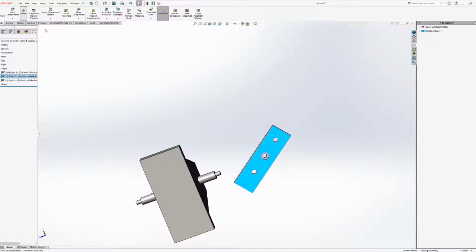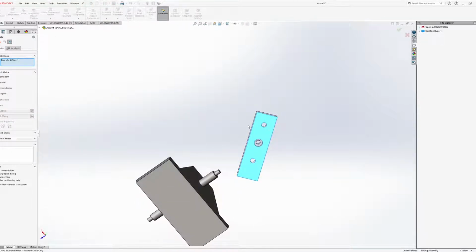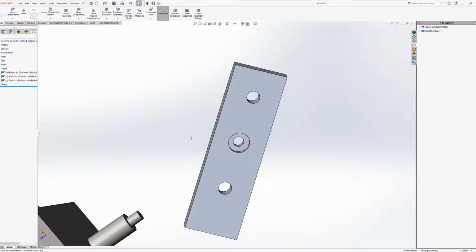I know some of you are probably yelling at me already. I said we don't want this kind of nested structure of mates. However, sometimes, and oftentimes, it will be acceptable. So yes, generally speaking we do want a common reference or a common mate between all the other parts, one thing expanding out to several different parts, but this is okay. This is acceptable. We'll be able to gauge why very soon.